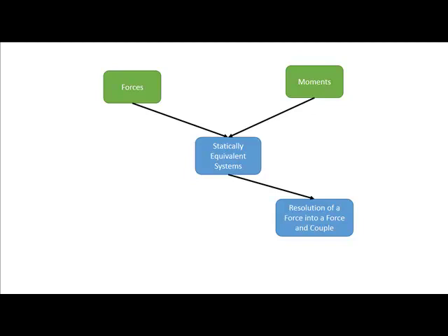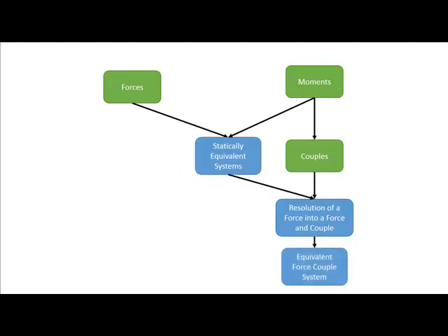And so the resolution of a force, basically we move the force, but that's going to change the moment. And remember, a pure moment is called a couple. It's a set of equal and opposite forces, so it has no net force, but it does cause a moment. And so if I move the force, I'm going to wind up correcting the point of application with a couple that I add to the system. So if I want to have some set of forces and I want to simplify it, I use this resolution of a force to find the equivalent force couple system.